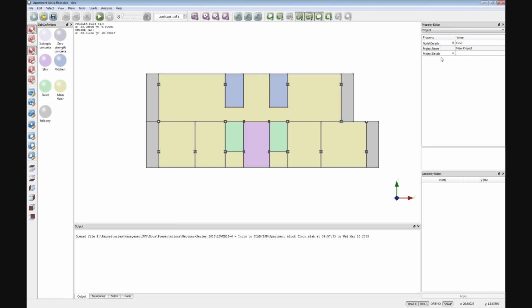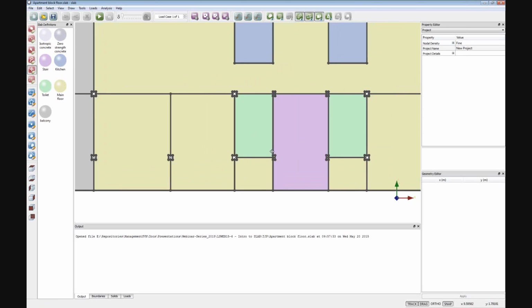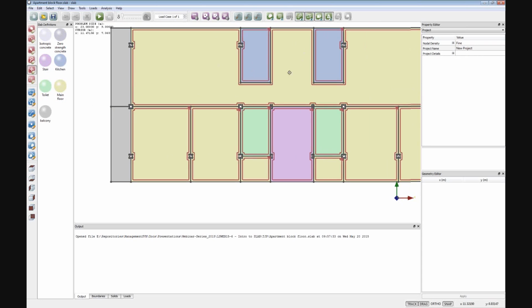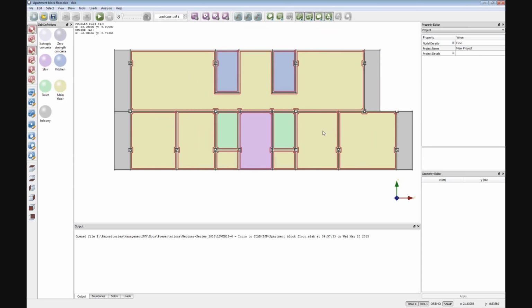So you can see here that it's the same problem, but now we have the material properties applied to each of the different zones. So you can see the columns are supporting it. There's actually no support around the edges to speak of, and we've got separate material properties for the different parts of the structure. If we click on the loading, you can also see where the pressure loading is applied, and if we wanted to apply sort of point loading in different positions, we could also do that.